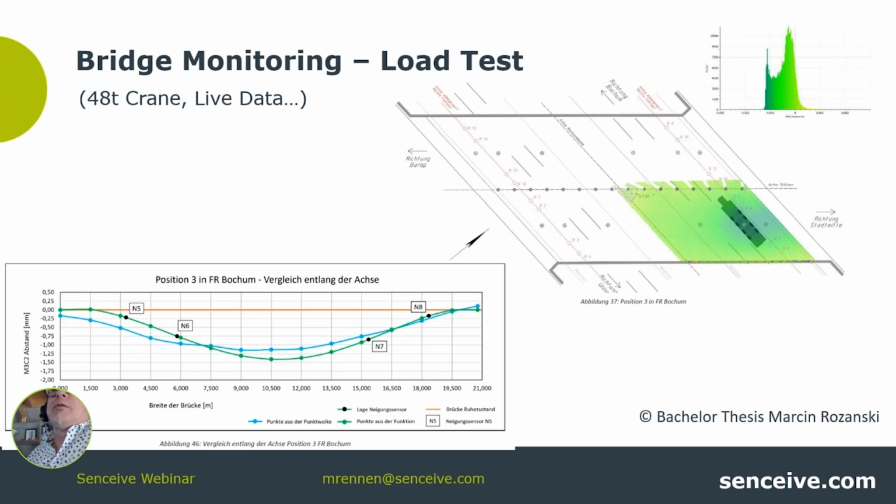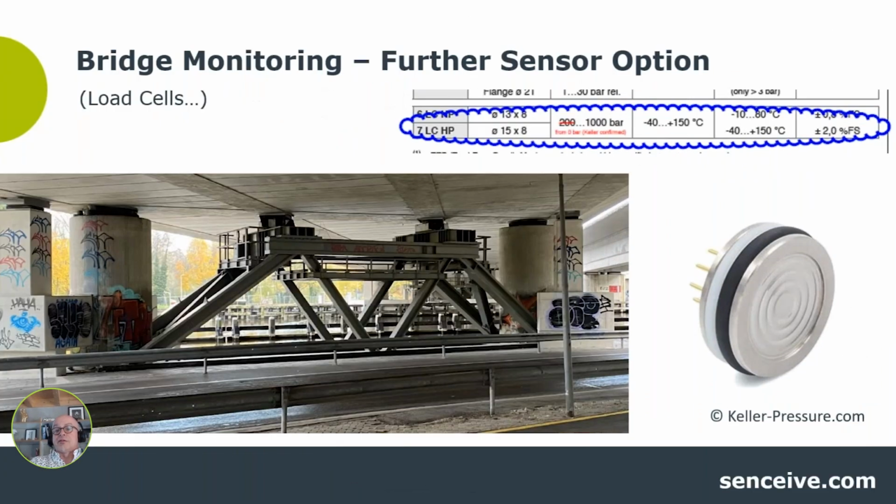Basically, to finalize the whole thing, I showed here a number of sensors that can be connected. Of course, there's a huge variety of other sensors, like, for example, this is Rozennood Bridge near Amsterdam, where a supportive structure was erected underneath the bridge. And in order to determine when the bridge actually puts load on this structure, there are load cells like this one installed underneath.